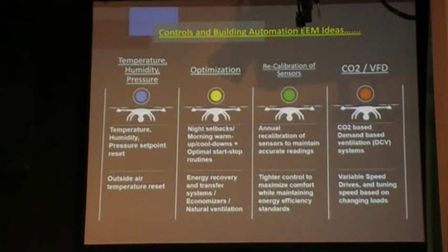And then finally, we do a lot of carbon dioxide, CO2 optimization in the U.S. So if the CO2 in the building is not so bad, then we can modulate the requirements of the ventilation coming into that building. Normally, in my practice, I can normally cut the ventilation 30 or 40% of the day, because people come in, they go, but as long as the ventilation systems are working well, that ventilation level is good, and so it stays good, and we can keep it.